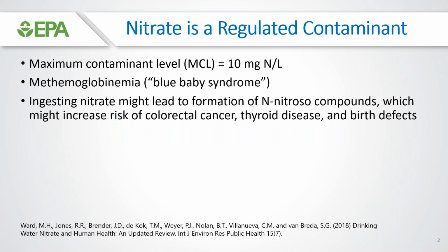So first, why nitrate? Nitrate is a regulated contaminant with a maximum contaminant level of 10 milligrams per liter as nitrogen. That MCL was set around the health concern for blue baby syndrome, because within the body, nitrate gets converted to nitrite, which can bind to hemoglobin, and then we don't have enough oxygen in the blood.